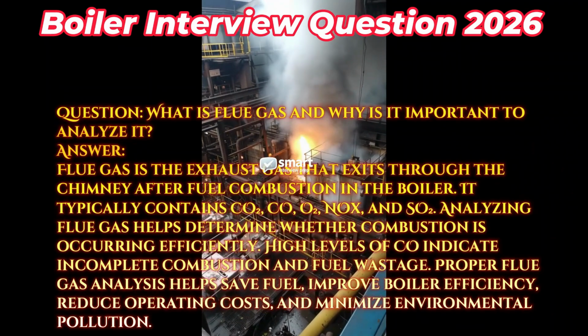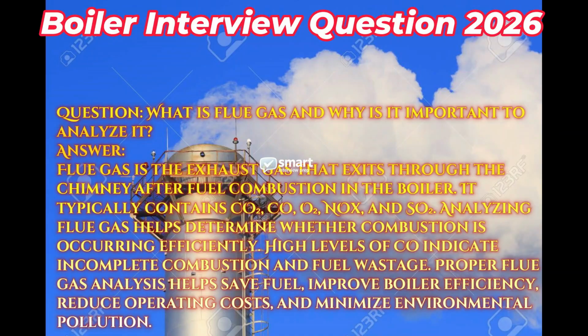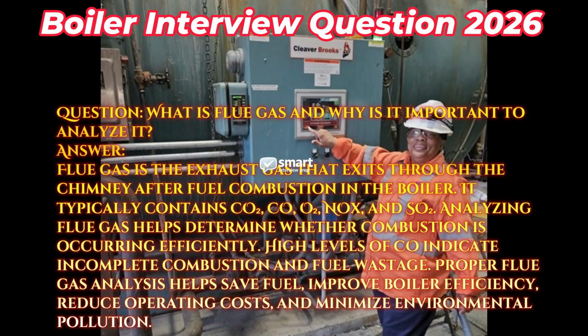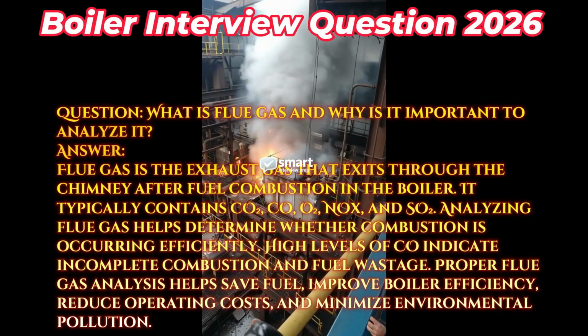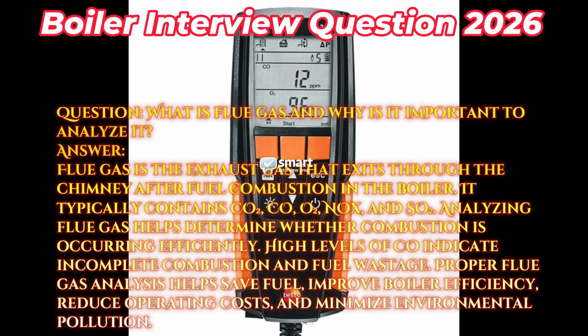Question: what is flue gas and why is it important to analyze it? Answer: flue gas is the exhaust gas that exits through the chimney after fuel combustion in the boiler. Typically contains CO2, CO, NOx, and SO2. Analyzing flue gas helps determine whether combustion is occurring efficiently. High levels of CO indicate incomplete combustion and fuel wastage. Proper flue gas analysis helps save fuel, improve boiler efficiency, reduce operating costs, and minimize environmental pollution.